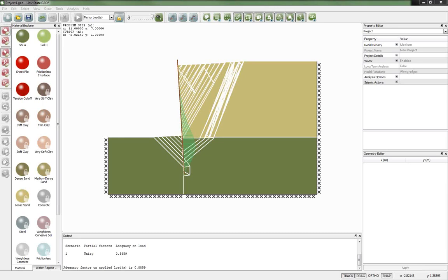So, for example, for a pile in a clay, typically to get soil to flow around it as a failure mechanism, it's around about 9 or 10 cu times the diameter of the pile. And you can enter that value into the software, and then if the software models the soil flowing past the pile, it will impose that force on the pile. So the software is able to pick the right size of mechanism, taking those factors into account. So that allows you to model that pile.